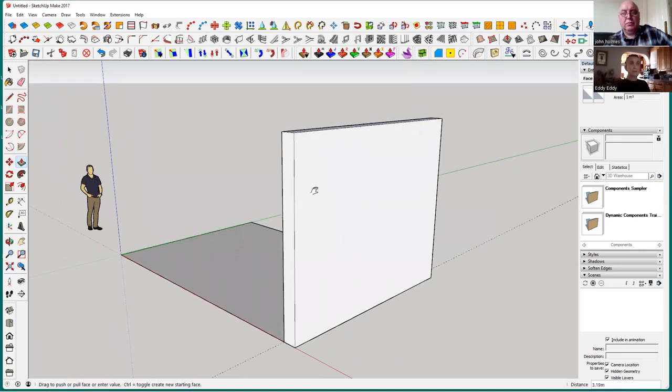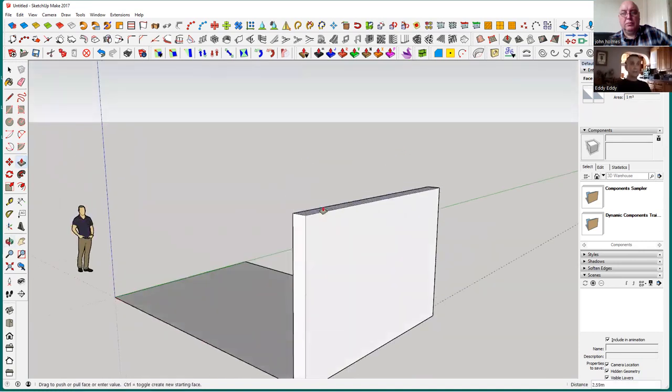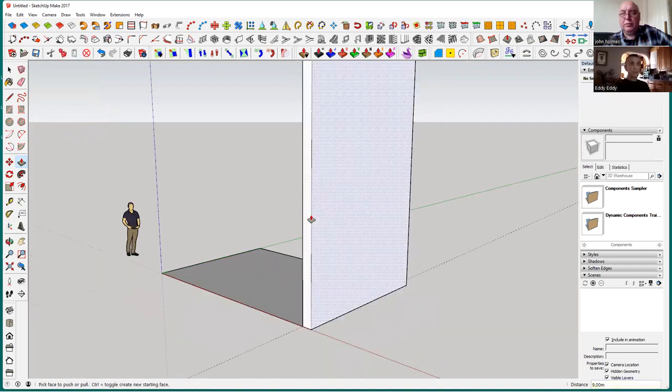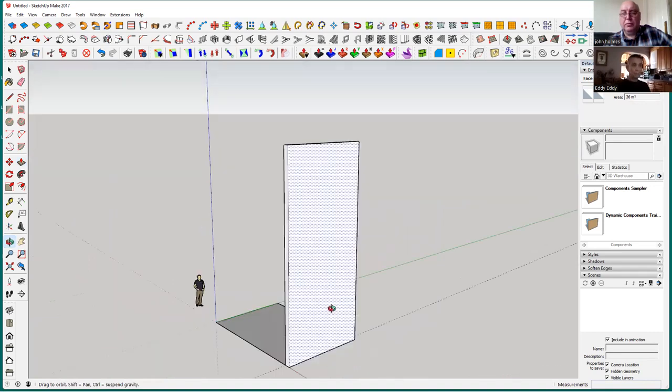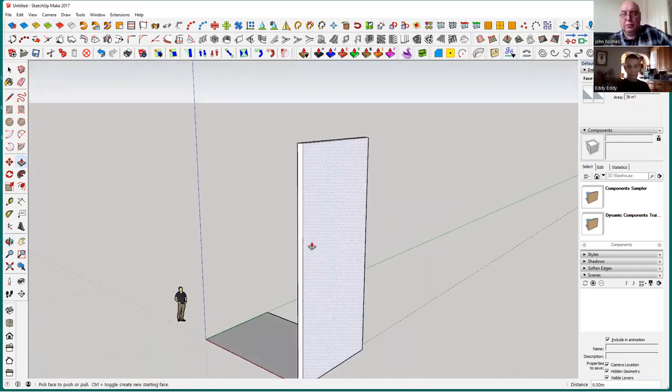So what we're looking at, 3 meters for the bottom floor, 2.5 for the top floor, plus the floor, 6 plus 3, probably 9. On the bottom right-hand corner, you'll see distance. So if you put 9, enter, that'll be our side wall. That looks a bit tall, doesn't it? We'll come down to 7 and see what it looks like.